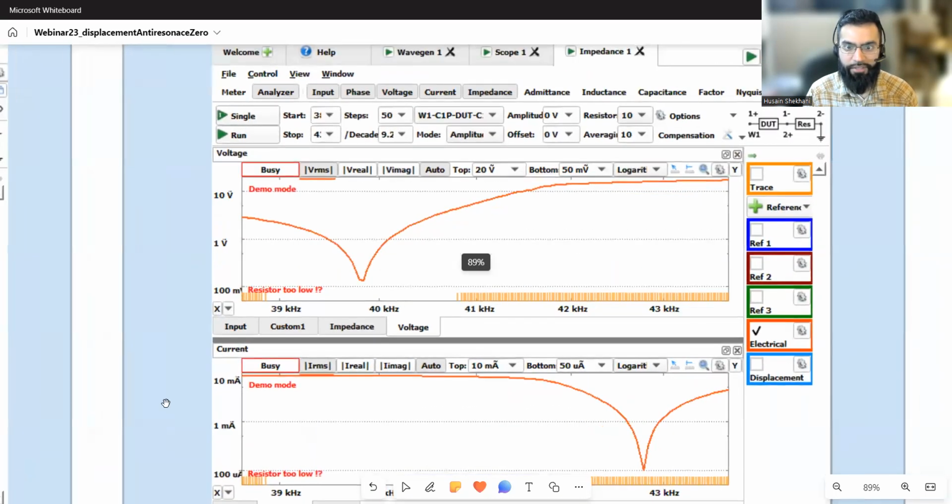Now this is where it gets kind of interesting, because I have that circuit there. The voltage and current are definitely not going to be constant. And mind you, the voltage is not even constant on a traditional impedance analyzer. Otherwise, you drive your 1 ohm load with like 1 volt, you're going to get 1 amp over your test device. No, your impedance analyzer has an output impedance. But in this case, with that transformer, I really even it out much better than even just a plain resistor or plain output impedance would.